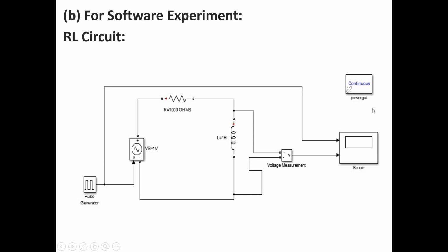You also require a powergui, so from the Simulink library, you must type powergui, POWERGUI, in the Simulink library, and you must copy it and paste it in your model. So you just copy it.